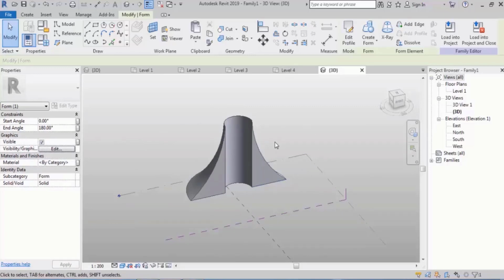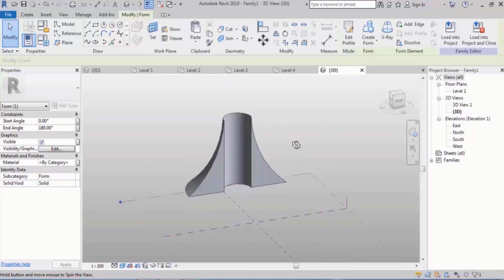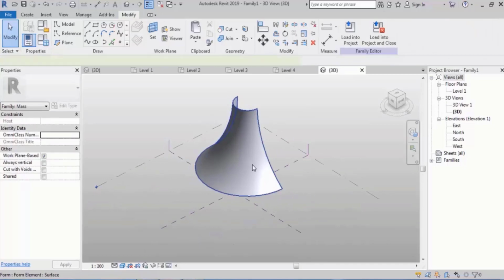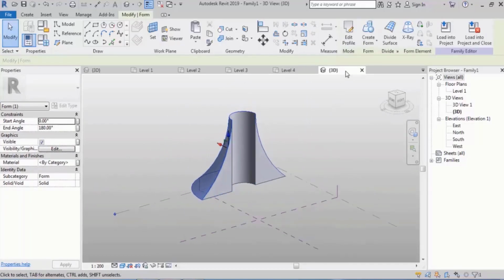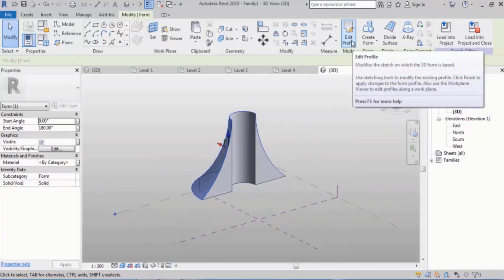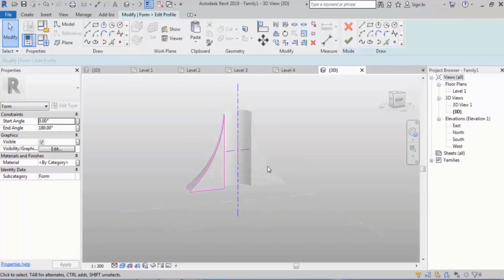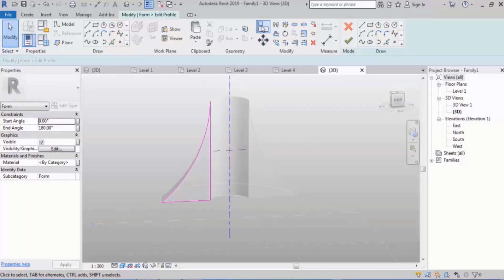Now, how can you edit it? When you design the shape, how can you edit it? Well, we saw the previous command's edit. It had edit profiles and so on until the end. Now, if you select your shell, any part of it, doesn't matter, again you see the edit profile. But the difference is that when you click on edit profile, you see that the structure of revolve is given to you: the form, the profile and the axis.